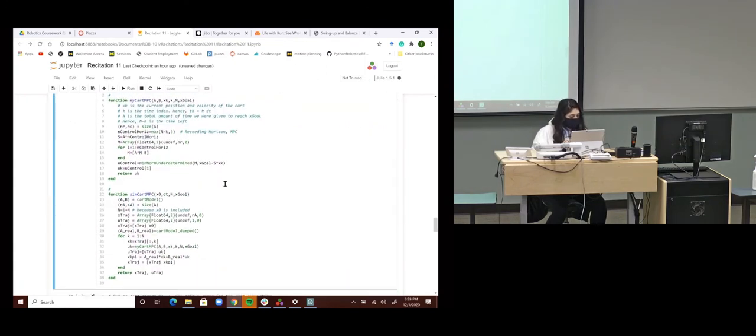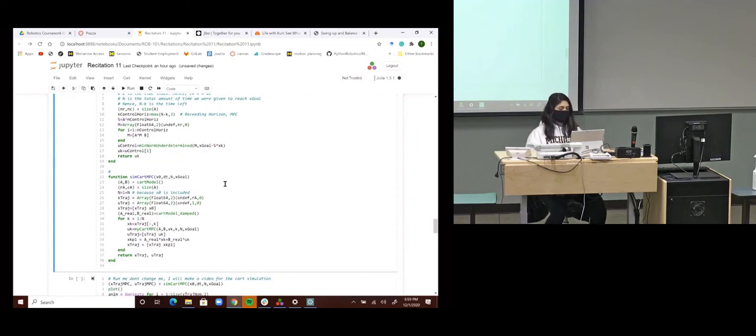But then from our project, we know that the idea is to use an MPC controller or any feedback control to be real. In a feedback control, you find one control sequence. From computing, this is basically our horizon, right? We say we're going to plan, I'm going to look, say, 20 steps in front of me, where I'm expecting to be in 20 time steps, which is like 2 seconds for us.